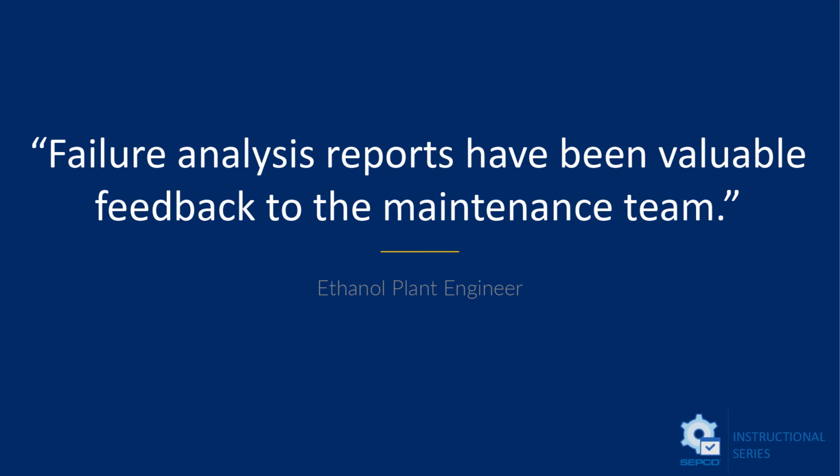We'll also give them some picture evidence to support the documentation so they can see exactly what was going on and what we found. And then there is the mode of failure, what caused that seal to fail. And then we also give them a suggested corrective action. What that is, that's telling them we see severe misalignment here. And if you're laser aligning your pump, maybe we need to go to the wet end of the pump and unbolt or unflange the loop. Start looking for pipe strain, bolt binding, soft foot.